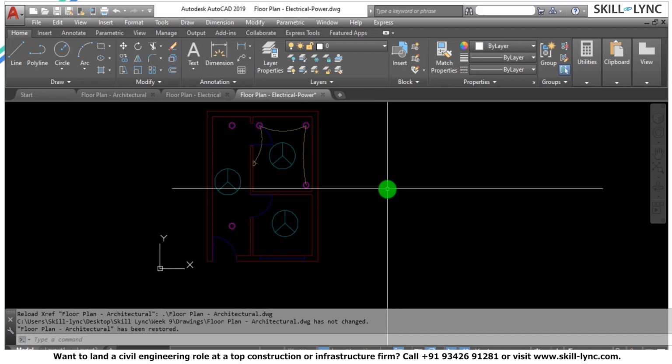So sometimes there is an Xref within an Xref. So this is an Xref, and within this there is another Xref. So it is called nested Xref. So now you can see the ripple is going, right? So this is how Xrefs are done.